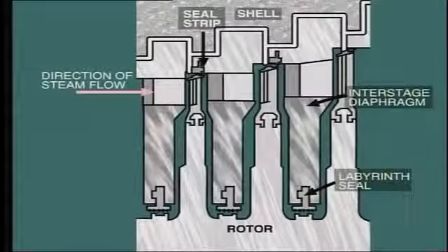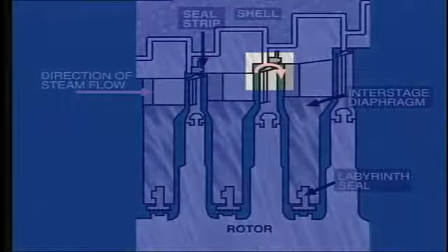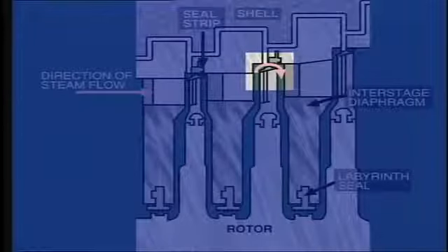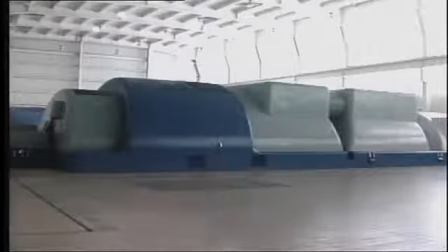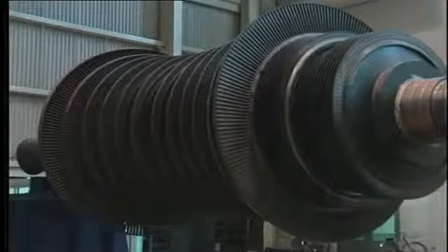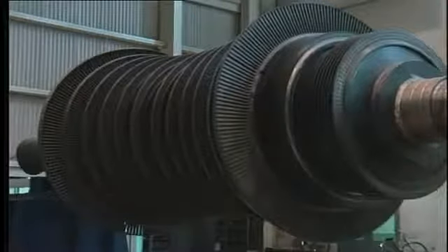Although the reaction turbine is efficient in its use of heat, there is always the potential for some losses due to steam leaking around the periphery of the moving blades, especially in the high-pressure section. In order to reduce this tendency, a reaction turbine will normally have many more stages so that the pressure drop in each stage is lower. Consequently, the machine will be physically longer. In practice, a compromise is reached, and today most turbines combine both types, using impulse blading in the high-pressure stages and reaction blading in the low-pressure stages.